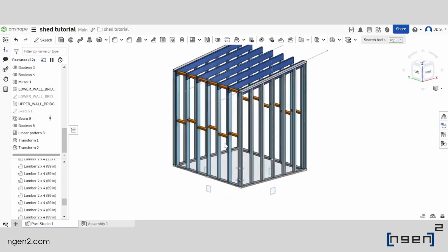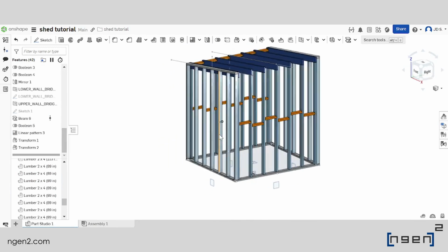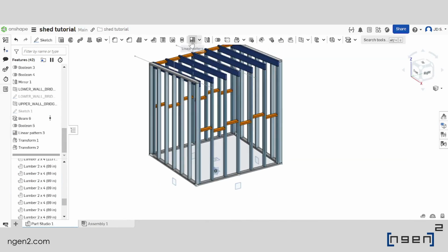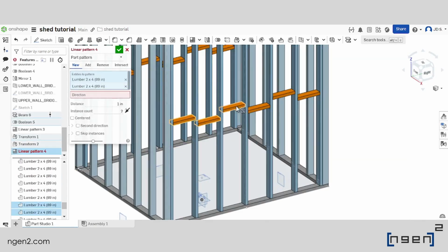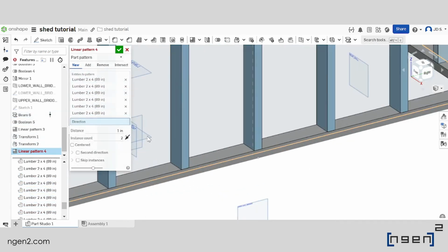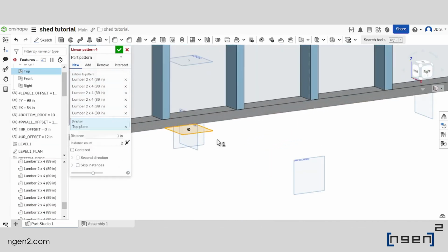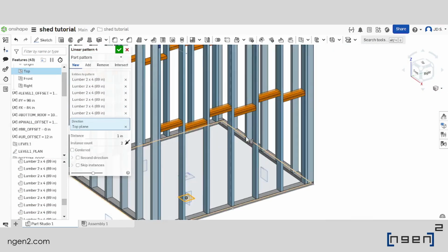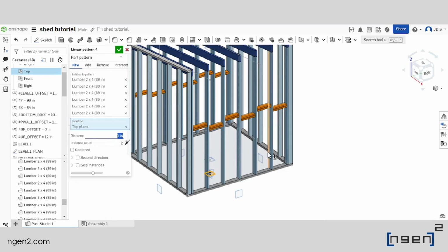We will repeat the same step for the other side. Except for this side, we will use the top reference as bottom roof elevation plus the upper roof offset minus the level 1 offset.